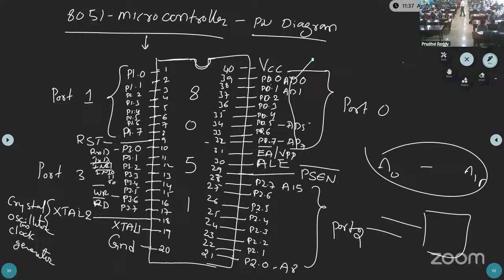Okay, now you can remember. Come to the point. The 20th pin and 40th pin we are using for the power supply, and 20 is the ground, and VCC is the plus terminal of the battery or adapter. Okay, next, any other pins? The next one, 30. Write down. 30 is ALE. The abbreviation, full form is address latch enable. Make it first. ALE is address latch enable.